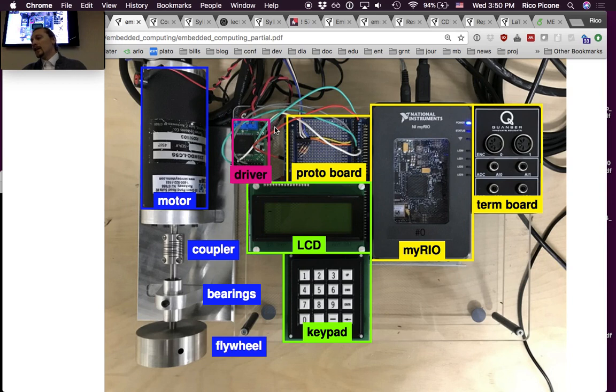we've tested it out. If you're going to mass produce it, you're going to want to have your own board. But if you're not going to mass produce it, if it's a small system that you're going to build 5 of, you might not. You might just use these evaluation boards, because they often come with all the right circuitry for interfacing it. The protections are on there, temperature shutdown sometimes. They're really convenient.